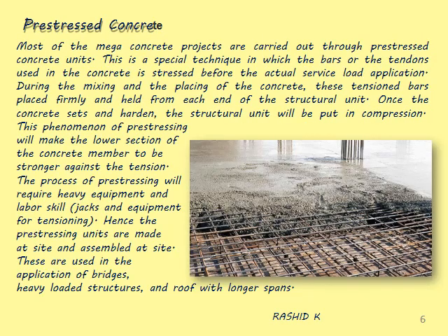We shall look at the pre-stressed concrete, and here most of the mega concrete projects are carried out through pre-stressed concrete units. This is a special technique in which the bars or tendons used in the concrete are stressed before the actual service load application. During the mixing and the placing of the concrete, these tension bars are firmly held from each end of the structure unit. Once the concrete sets and hardens, the structure unit will be put in compression.